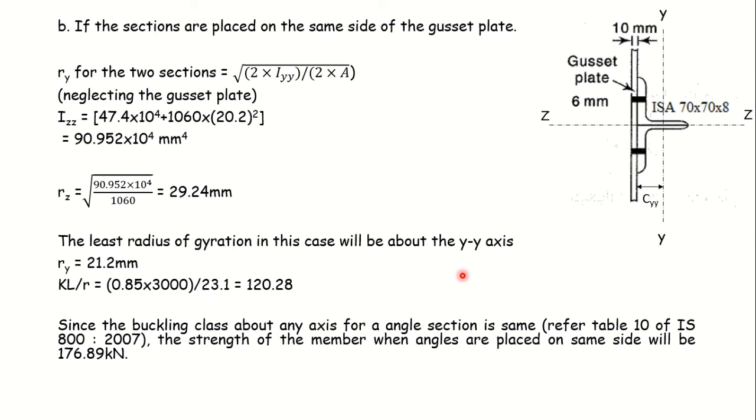Then from that you need to obtain phi and find FCD. Or else you can go ahead with getting the stress reduction factor chi from table 8C, and alternatively we can use table 9C, what we have done in this example over here. That is, you can find FCD directly by using table 9C.